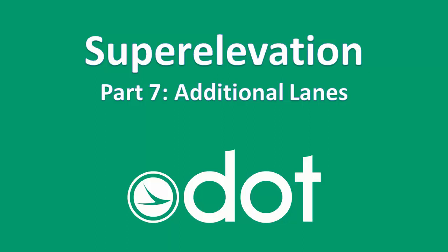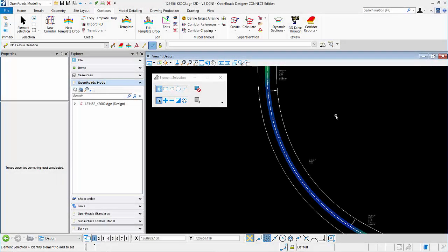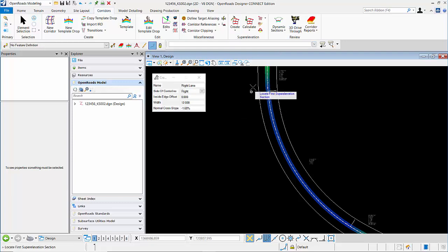In this video, I'm going to demonstrate the process to add an additional lane to our superelevation. So I have a superelevation definition here, and there's a couple different ways I can add lanes. I can add a lane for the entire length of the alignment, or I can add lanes for only a portion of it. So in the Create tools under Create Superelevation Lanes, I can come in and add a lane